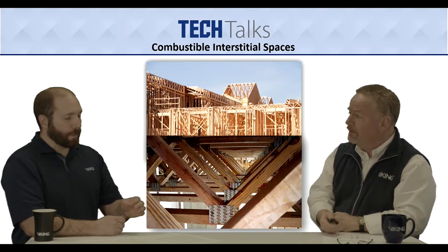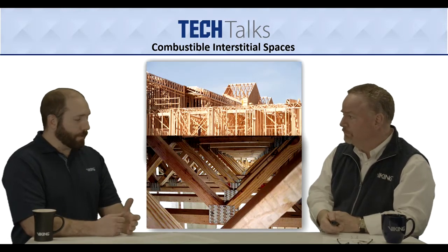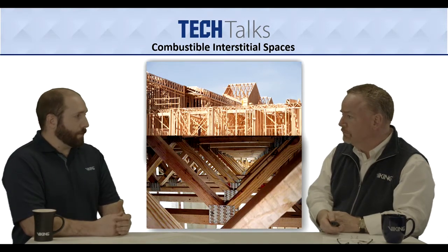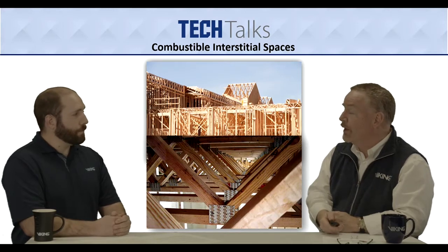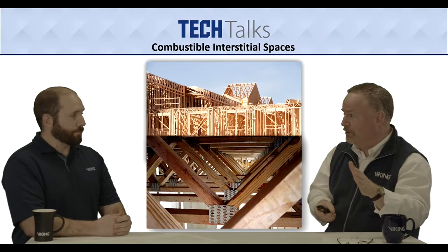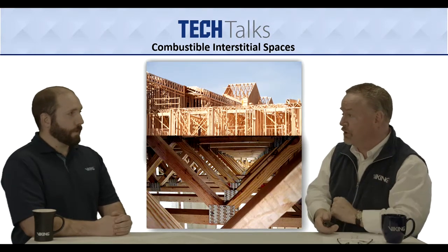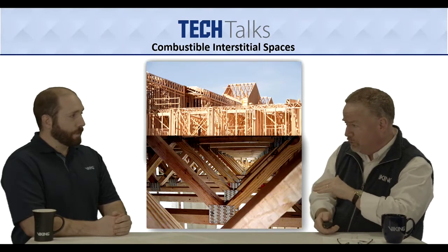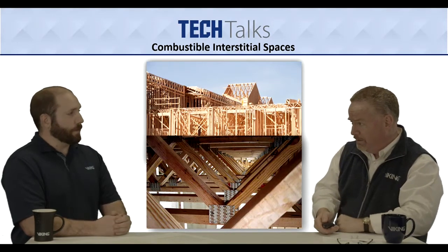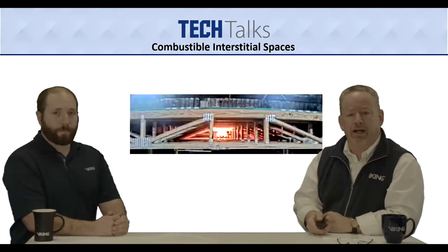Yep, and the key word there is combustible. So you've got those horizontal runs between the floors, even low pitch attics up to a 2 and 12 slope. Okay, so that's something we're going to talk about. Attic sprinklers later, those are kind of a different animal. They're used under different slopes. So this can be used, what was that again, 2.5? Up to 2 and 12 slopes. Oh, 2 and 12. Yep, low pitch roofs. All right, so let's take a look.